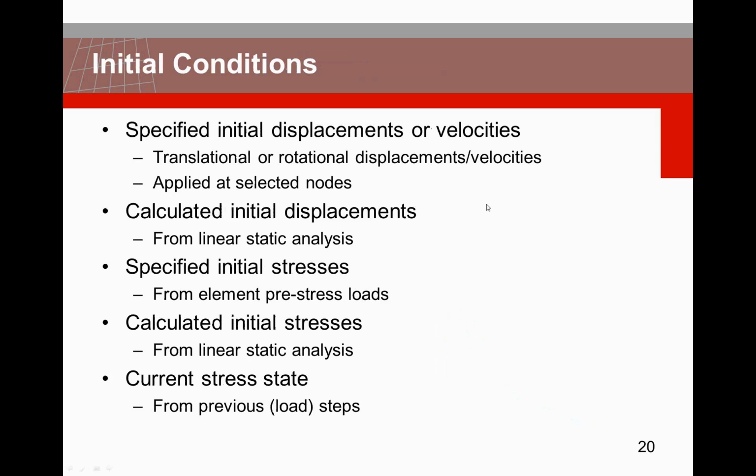Next thing, what's still interesting in the modeling part are the initial conditions. This can be initial displacements or velocity, translational, rotational. You can apply them at the nodes. You can also calculate initial displacement from a linear static analysis.